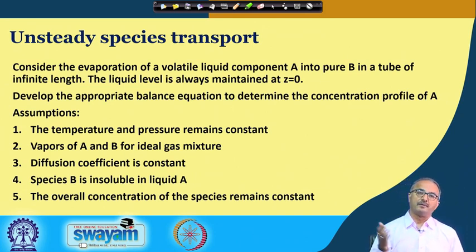Or for example, when we are trying to dry some kind of material or clothes, we put some fan to make it dry faster. And why do we do that? Because when this particular component is evaporating from the wet surface, it forms a mass transfer boundary layer near the surface, okay, and that creates a resistance to the mass transfer or evaporation.